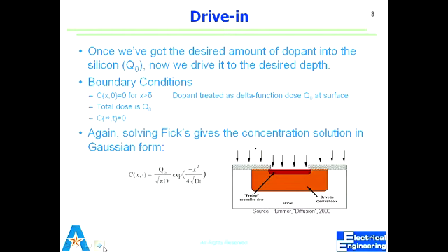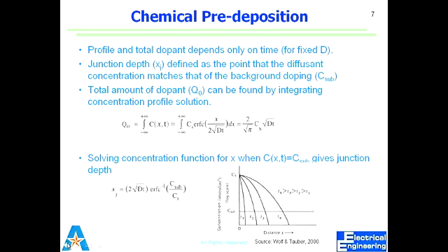Now, you guys haven't looked at implantation yet, or you have seen implantation already? Implantation gives us that advantage where you implant the dopants directly and the profile is Gaussian. So instead of a distribution which is like this, what we have with implantation is something like this. So we can control how deep the highest level of dopant concentration should be.